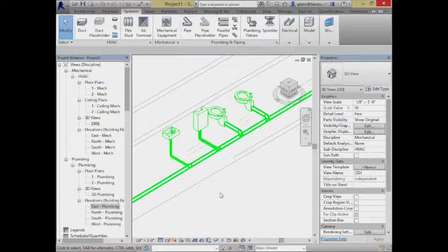So I would recommend a strategy of what I'll call hybrid auto routing, where you don't give it complete freedom to do whatever seems to mathematically make sense. You use your intuition as a designer to lay out a pretty close to sensible path, and then you let it optimize the endpoints. Because you'll just get a better result that way. You have a lot of intuition about what you had intended and how the piping would probably make the most sense. Revit doesn't have that intuition. It's just a mathematical equation to it. So give it a little bit of guidance in terms of what's going on.